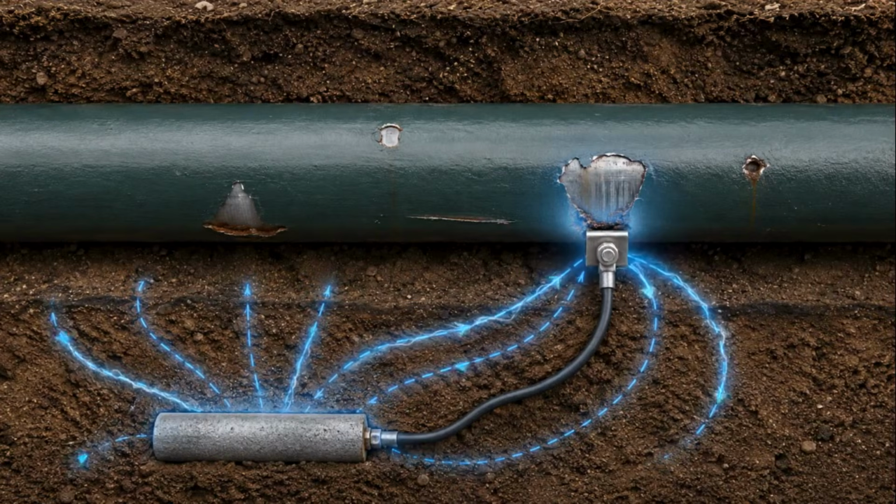Cathodic protection is a method of protecting metal by making it behave like a cathode. Remember, the anode corrodes. The cathode is protected. So the basic goal is simple. Make the steel structure the cathode. To do this, we supply electrical current to the structure. This protective current changes the electrochemical condition of the steel surface. Instead of allowing the steel to lose metal at anodic spots, we force current onto the steel. That helps reduce corrosion. In simple terms, cathodic protection does not create a magic shield. It uses controlled electrical current to reduce the corrosion reaction on the protected metal.